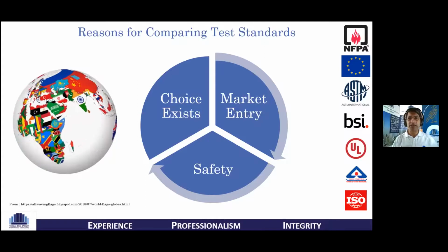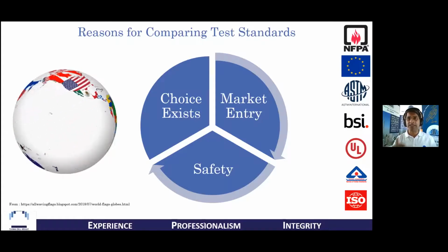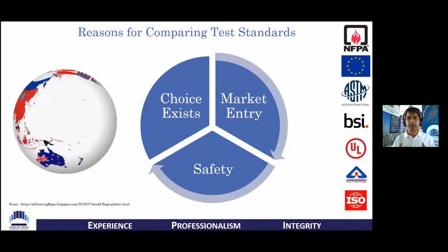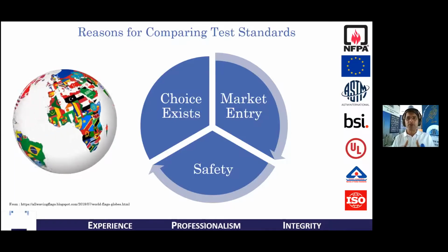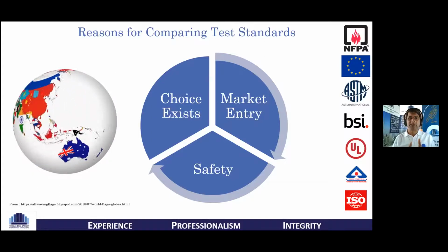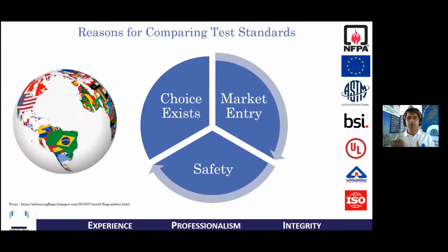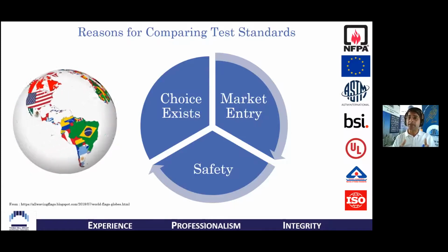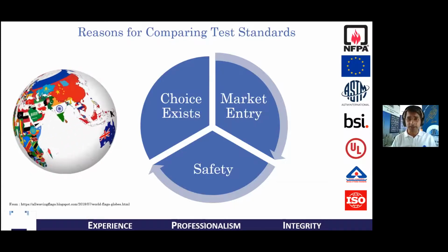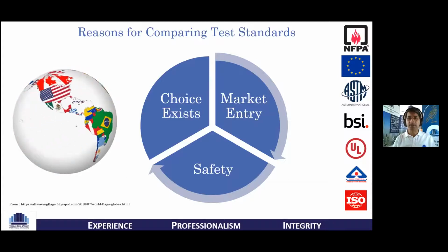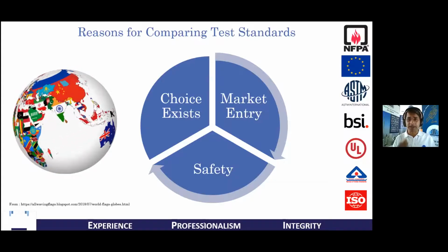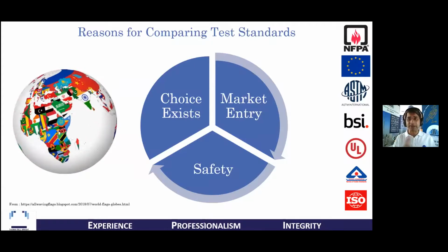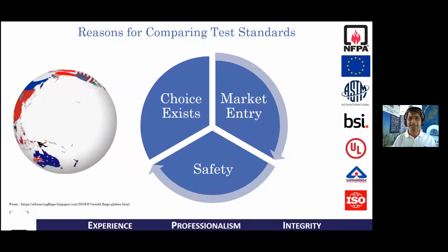You cannot come up with a concept of egress or evacuation as per the European code and have a fire door or a partition tested to the American standard with components which comply to British standards. It can be done, and I'm not saying it does not work, but it will always require a microscopic view, someone who really understands the interplay between these standards.